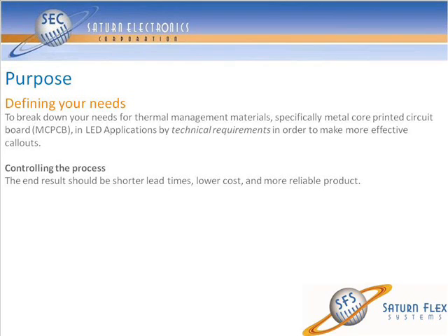What I see is a lack of specifying actual critical needs and an abundance of specs that I consider either dangerous or potentially creating waste. A proper fab note should not only define your needs, but also bring concrete benefits: shorter lead times, lower costs, and higher reliability in your product.